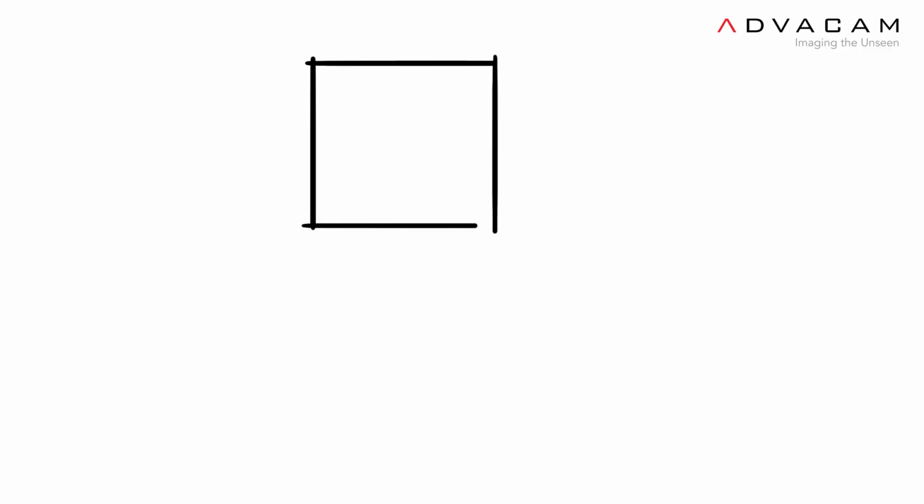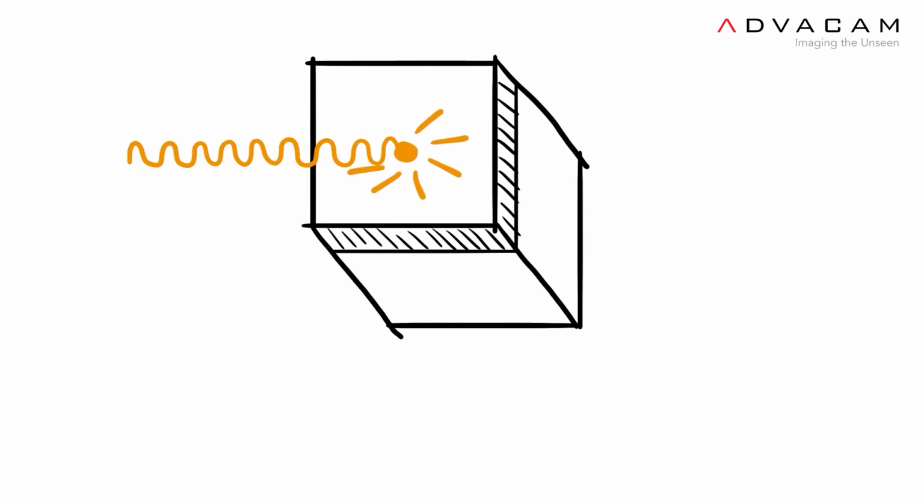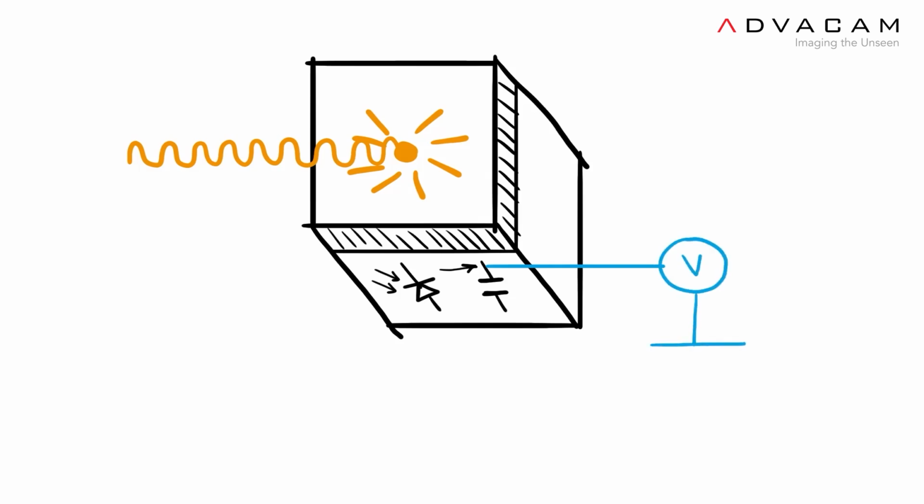A flat panel detector is used, for example, in hospitals. Its surface is covered in scintillating material. When it comes in contact with X-ray radiation, it converts it into visible light in an analog process. The pixel starts to glow. The next layer contains a photodiode, which converts the light into electrical signal. The current created by the diode is accumulated in the capacitor, and the charge is measured by a digital voltmeter, which gives out digital information about the pixel. These values together form an image.